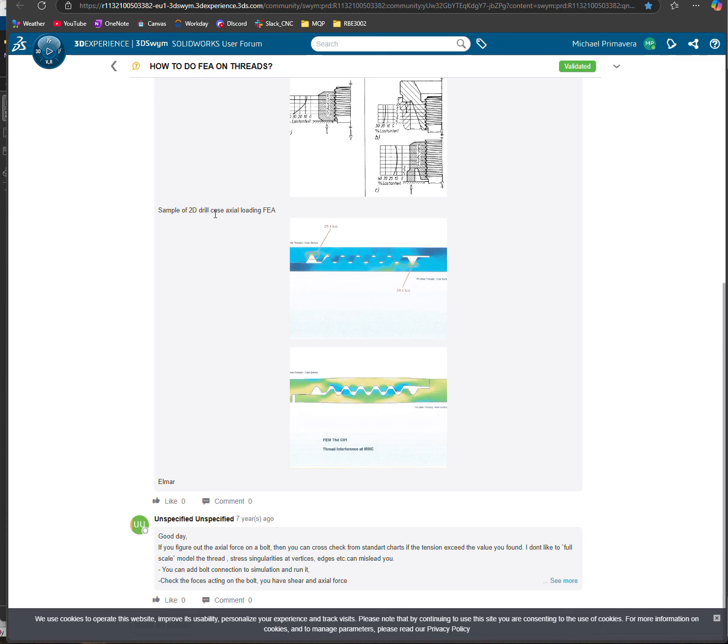From what I read, long story short, the formulas have stood the test of time. The simulations are somewhat tricky when it comes to threading because of things like surface area engagement, and the fact that the first thread will bend in reality when there's a force on it, and the sequential threads will get less and less force applied to them as it goes down the chain.